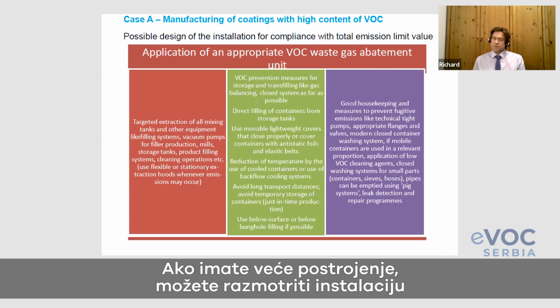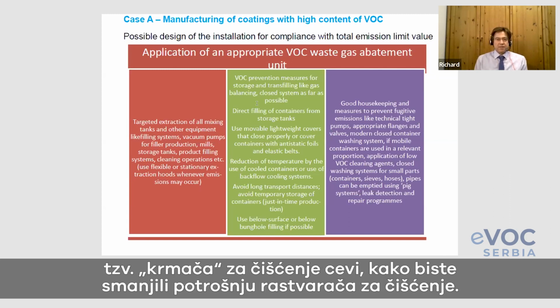If you are operating, I would say, on a larger scale, you can think about installing pigging systems. If you have to change products and you have to clean your pipes, you can use those pigs to reduce the solvent consumption for cleaning.